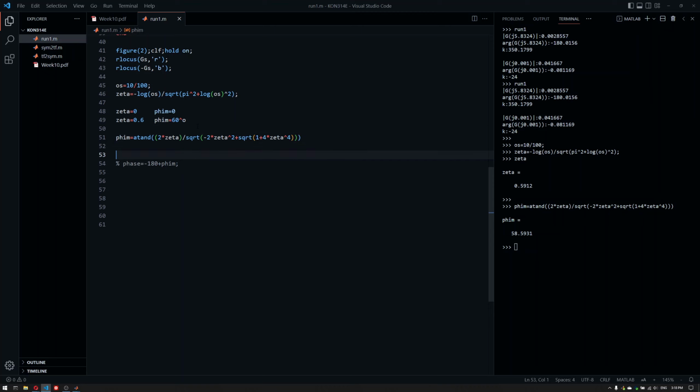And we're trying to do this, but with phi m, the phase margin. So instead of making it exactly equal to 1 at the minus 180 degrees boundary, we're just shifting the phase value by this margin. If we shift it enough and accurately, then we should end up with the controller that has the overshoot we're looking for. But the bad news is that this should hold for second order transfer functions. So this might be a little bit off when we calculate it.